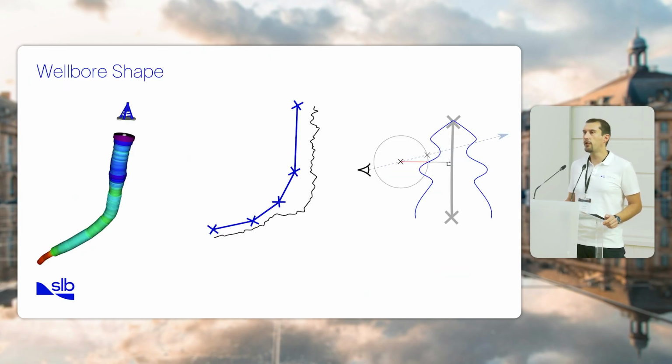Now let's have a look at the last shape, the most complex one. The Wellbore shape is composed of the polyline of the trajectories and a well log. This is the log of the caliper all along the trajectories. And here the idea is to try to create a signed distance field to represent this shape. I identified a way to have the exact signed distance field, but I can easily compute an approximation.